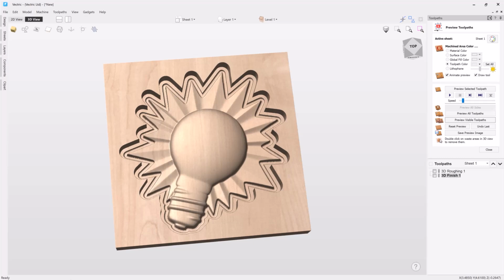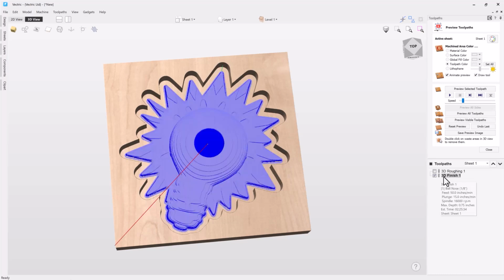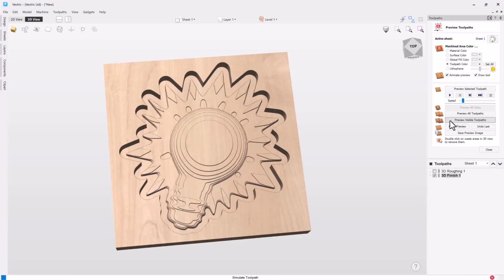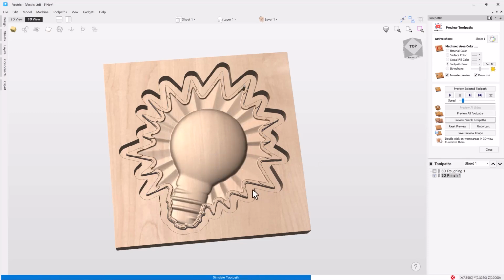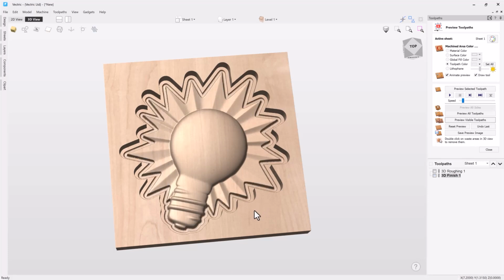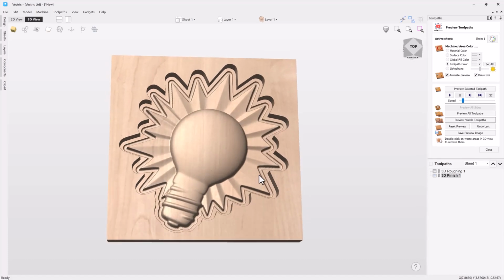Although it is not always needed to have machined or cut a 3D roughing toolpath before you run a 3D finishing toolpath, it is the most commonly used workflow. A 3D finishing toolpath is used to remove the machining allowance left by the roughing toolpath, revealing the detail of the 3D carving. The 3D roughing toolpath does the work to remove the lion's share of the material using a large cutter before the 3D finishing toolpath goes in with a smaller cutter or a combination of smaller cutters to do the rest of the work.